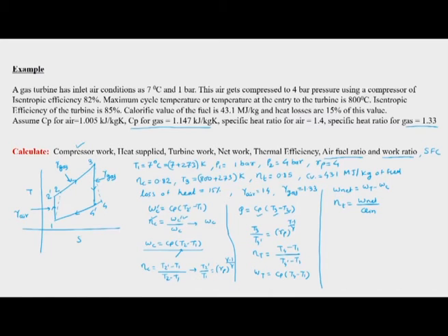The Q we calculated here is the Q which is actually received, but Q in is the supplied energy, and this is supplied more since there are losses of 15%. So this is W net upon Q divided by 0.85. This would increase Q by accounting for the losses.